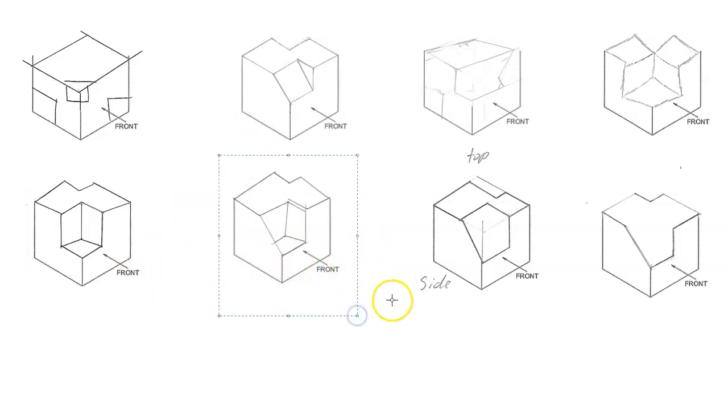The next drawing here, I'm also giving 2 marks, even though the front, top, and side views all look correct, more or less. This corner is actually wrong. It's not an omission. It's actually wrong, and that means that the student has had a misunderstanding of what is going on here. There's a point where they should be able to recognize that this line disappearing into nothing is a sign that you've done something wrong, and to reevaluate and to go back and look at the picture.